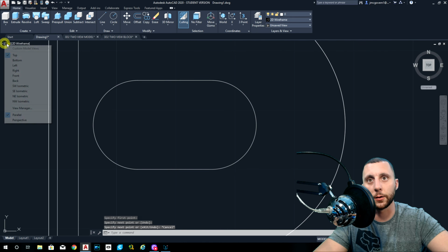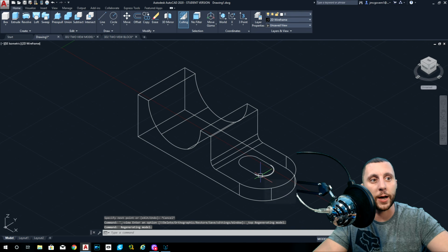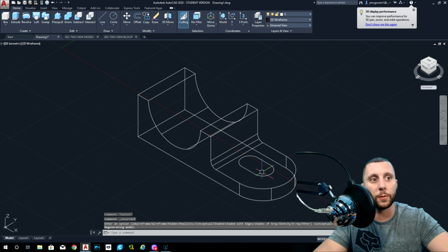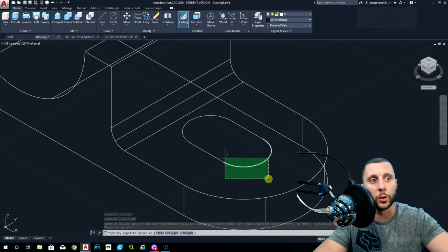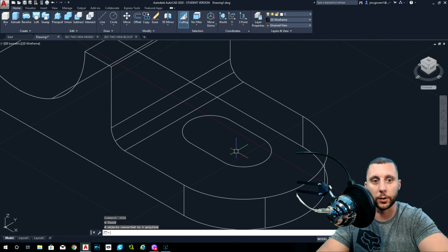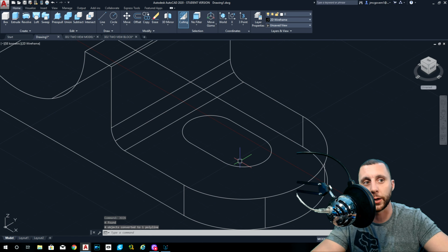But again, go back to the top, bottom right corner. It's only on the top. It's not cut out yet. So what we have to do is we have to make this its own little profile, just like we did with the front of this shape. We're going to take 1, 2, 3, 4 and type join. And we're going to look at the bottom, and we're going to make sure it says 4 objects converted to one polyline, which it did.